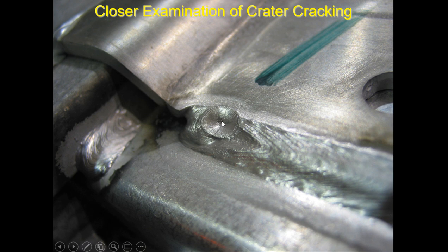And if you look in the center here, interesting, because it didn't have the fill, it was left very hot. There is some black oxide that's formed right there. I have a good picture coming. It's probably one of the better pictures of oxide you'll ever see. But there's a chunk of black oxide in the middle. That's key. That's a key repair. That's got to get fixed.